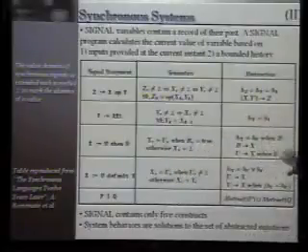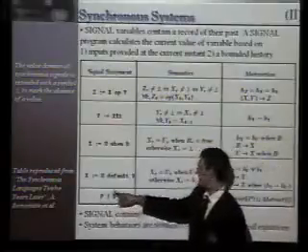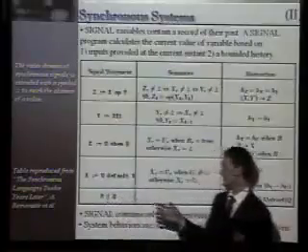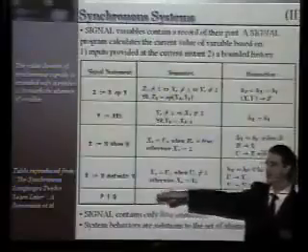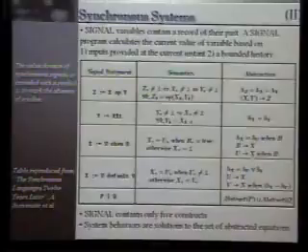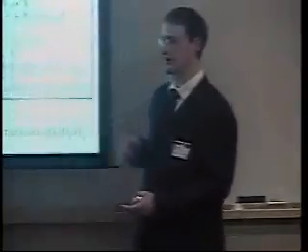These are the ways they're abstracted into causal information. And now, to build a big system out of a whole bunch of these statements, you need a way to compose statements together. And the composition is very simple. You translate each p and q into its equations, and you just union those sets of equations. So from the synchronous reactive model, you capture events, you capture functionality, you capture scheduling with just these four constructs plus a composition mechanism.